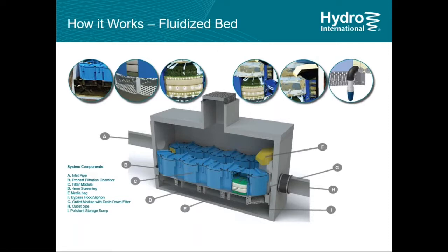It's the last to the right on the upper top there. It's this 90-degree bend, and it's got a little filter at the end of it. That is a drain down, so we want to make sure that our media remains dry. That filter actually drains down the water the last few inches to get it below the media bed level, and accommodates that 9-inch drop I talked about.